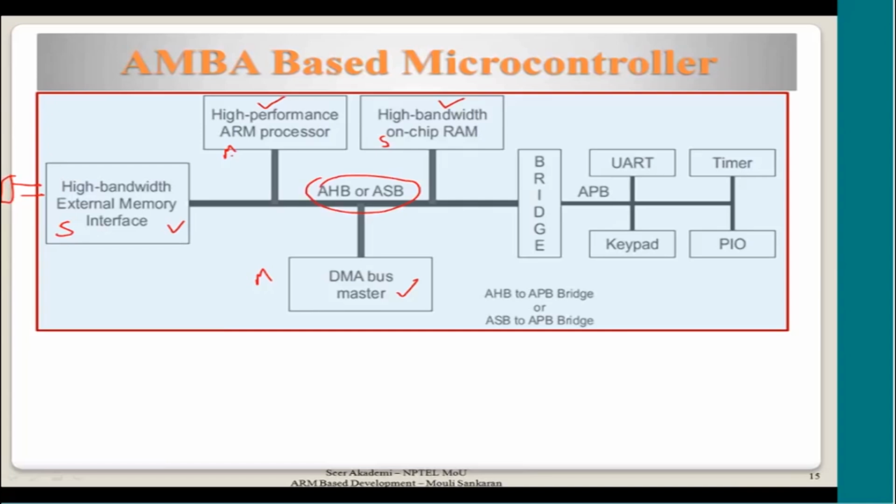Now this master is the one which initiates transactions on the bus, and the slave responds with whatever the master asks for. This master could also communicate with a peripheral. So you might have written some code or a device driver interface for connecting to the UART. So the ARM processor is talking to the peripheral, trying to write one character into this particular register on the bus.